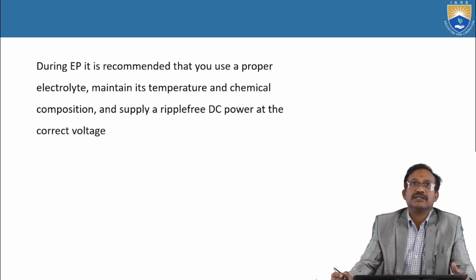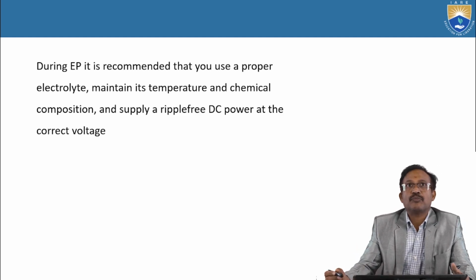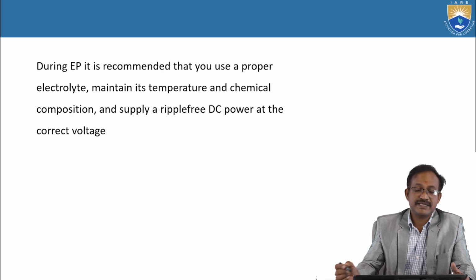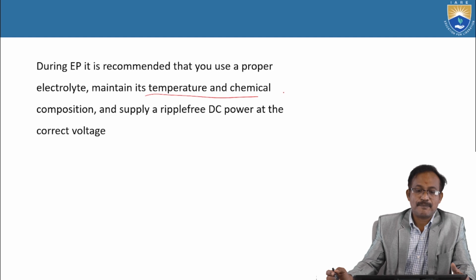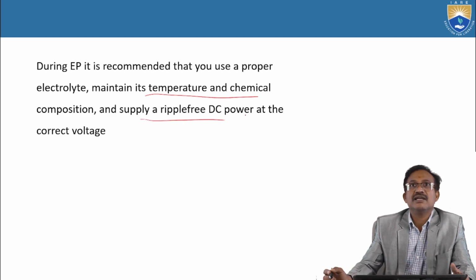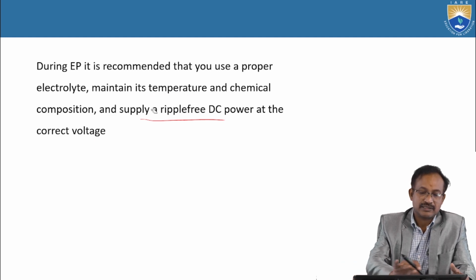During electropolishing, it is recommended that you use a proper electrolyte, maintain its temperature and chemical composition, and supply a ripple free DC power at the correct voltage.